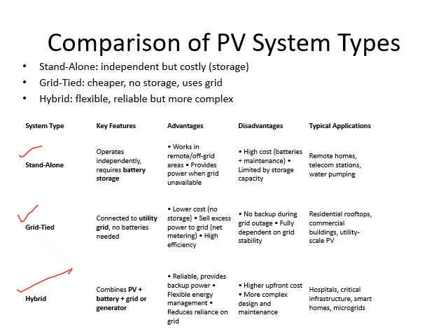And the grid tied, we know already that it will cost us lower cost, and then we will have the excess power to sell to the grid or somehow get some advantage from the grid. High efficiency, but the disadvantage is if your connection with the grid is somehow disturbed, then you do not have any backup during the grid outage, right?